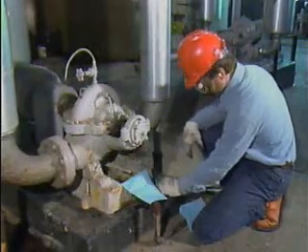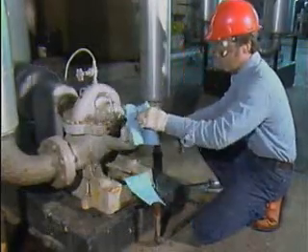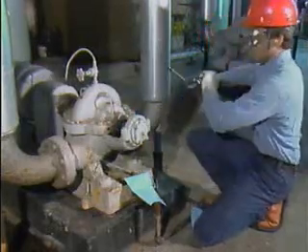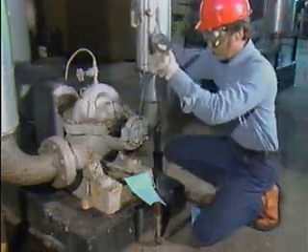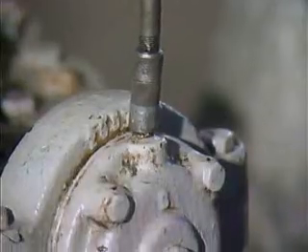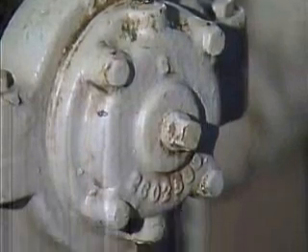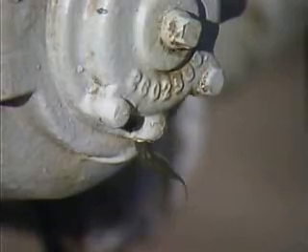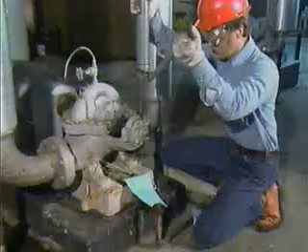remove the plug from the drain hole and wipe the grease fitting clean. Then, connect the grease gun to the fitting and slowly add the specified amount of new grease while the machine is running. Don't overgrease the bearing. Typically, with a hand-operated grease gun, you should apply no more than 3 shots of grease at a time.